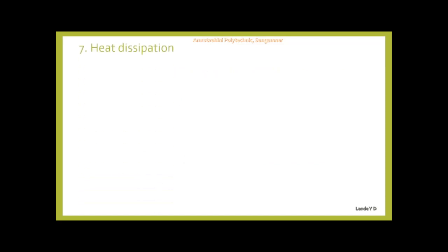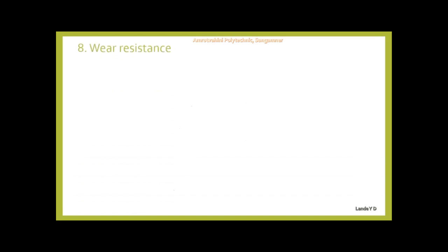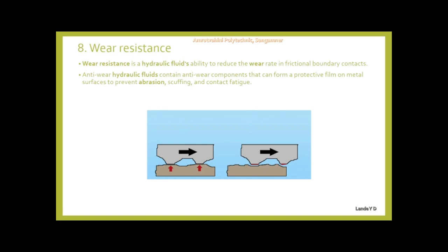7. Heat dissipation. An important requirement of the fluid is to carry heat away from the working parts. Hydraulic systems dissipate heat through the reservoir. 8. Wear resistance. Wear resistance is a hydraulic fluid's ability to reduce the wear rate in frictional boundary contacts.